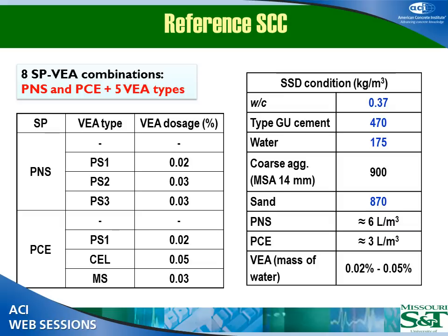Okay, we selected one mixed design, and this is a mixed design that is targeted really for precast applications. So precast applications could be structural applications, or it could be architectural types of applications. Like I said, the mix itself is very stable. It has quite a bit of cement, low water cement ratio, and aggregates are optimized, grading, etc. We are using very low dosages of VMAs to promote robustness.